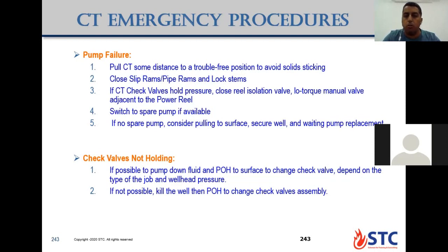So here we cannot continue our operation with a failed check valve. We need to pull out to change the check valve as soon as possible. First option, if possible, is to pump down fluid and pull out to surface to change the check valve. It depends on the type of job, what you are doing now or what you are pumping in the well, and also on the wellhead pressure for the well.